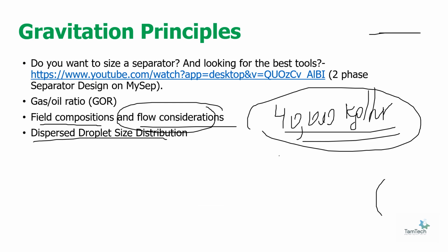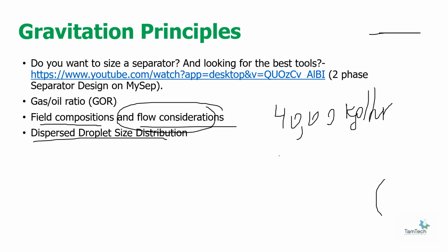So let's continue with the next principle, which is the flow regimes upstream of the separator. A mixture of gas, hydrocarbon liquid, and also water flows to the separator. I'll give a horizontal example. The mixture can exhibit various behaviors, like different flow patterns. What does it mean? It could be based on the elevation change, the difference in velocities, and phase densities. In each case, your relative flow rates will be changing.